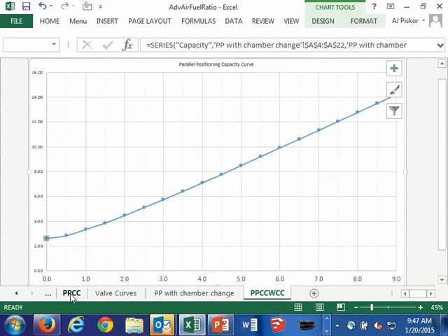If you've got a burner that has a very high air differential pressure and a very low gas differential pressure, obviously a change in combustion chamber pressure is going to be that much more critical to maintaining your air-fuel ratio, because now you've got a much higher gas flow going through if you have an extra suction in your chamber, and that's going to really throw your air-fuel ratio out of whack. So just all the more reason to mind your air-fuel ratio and your chamber pressures when you're adjusting your burner.